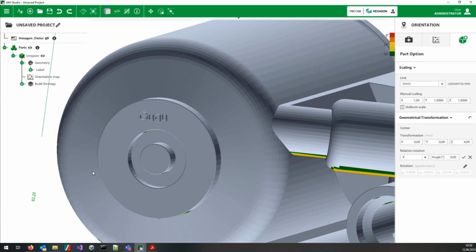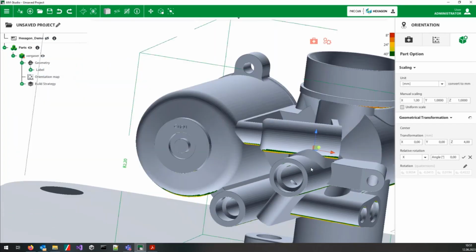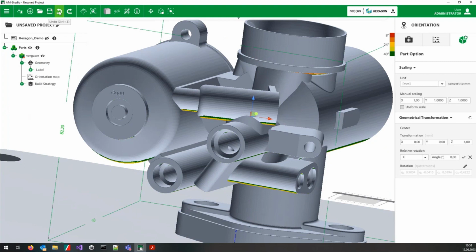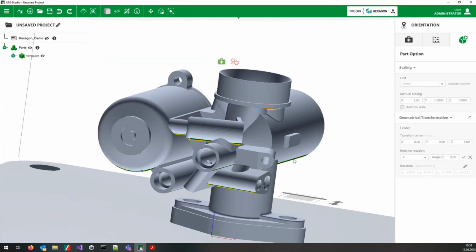That was the reason why you have seen already, again, the check for errors. So it's not the kind of thing where you can take this and move it around, because it has already changed the mesh here. So you have to be clear where to put it and what the text of it is. Otherwise, you have to go back and create a new label, as it's directly applied on the mesh. Maybe just remove it again.